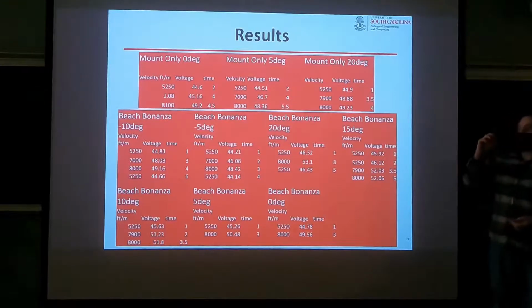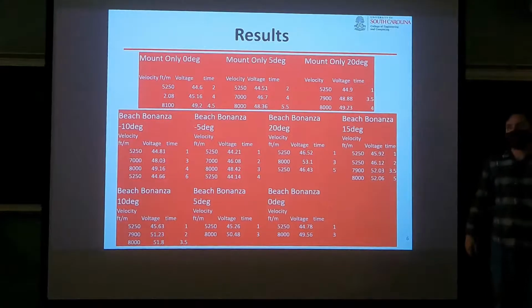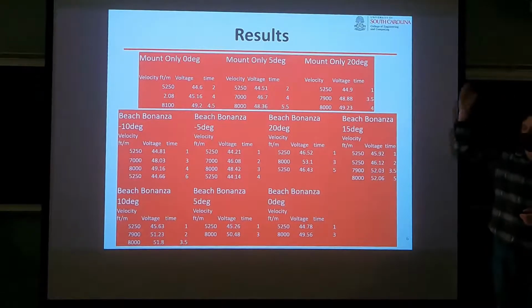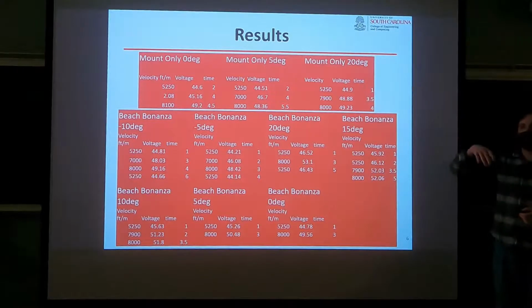We don't have an active computer DAQ system recording this data for us. So we just record the voltage directly, and we could use our other calibration data, which isn't shown, which is literally a graph of a ton of voltages over a period of 3 hours with about 40 different weights hung on the cell, to get some idea of what this voltage actually means force-wise. It's about the difference.